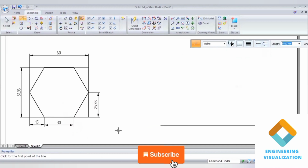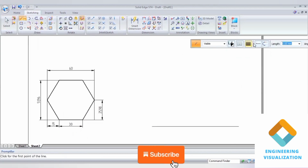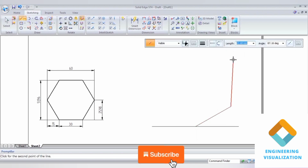Take a reference line. From this reference line, construct a box for a length of 51.96 at an angle of 30 degrees. The second length is 60, angle is 150. Again the length is 51.96, angle is 210. Okay, now join. So the box is constructed.